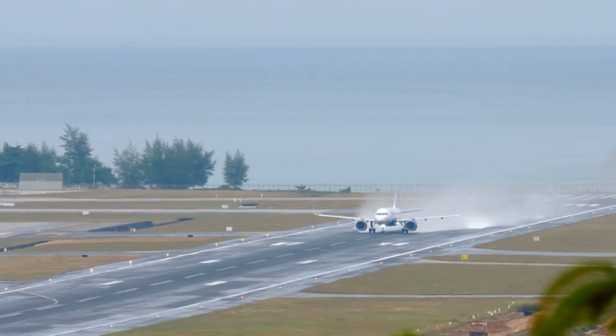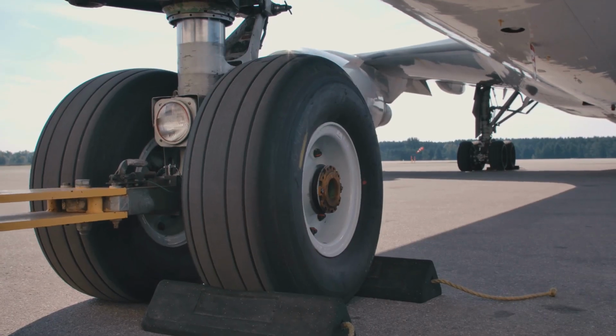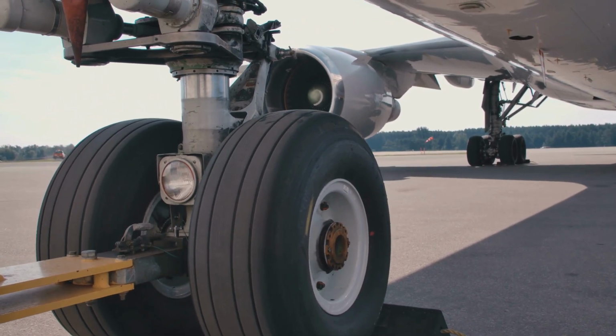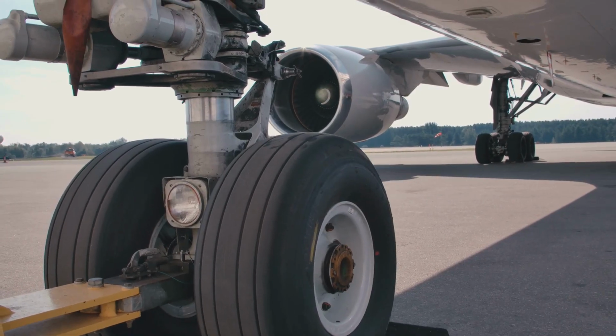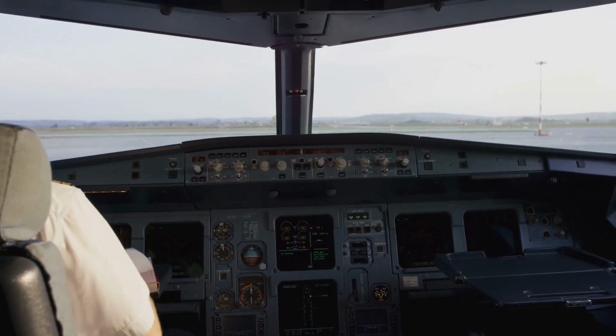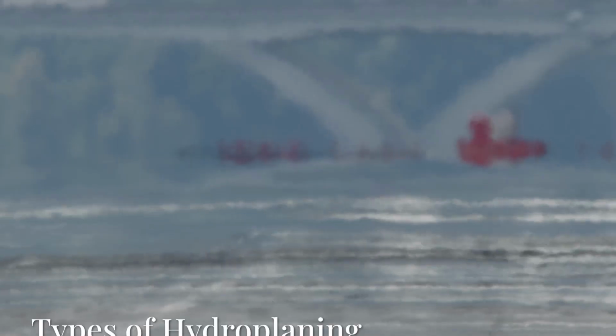Loss of traction. When the water layer is sufficiently thick, it generates a force, dynamic pressure, that can lift the tires off the surface, leading to a loss of friction. This results in the aircraft being unable to steer or brake effectively.